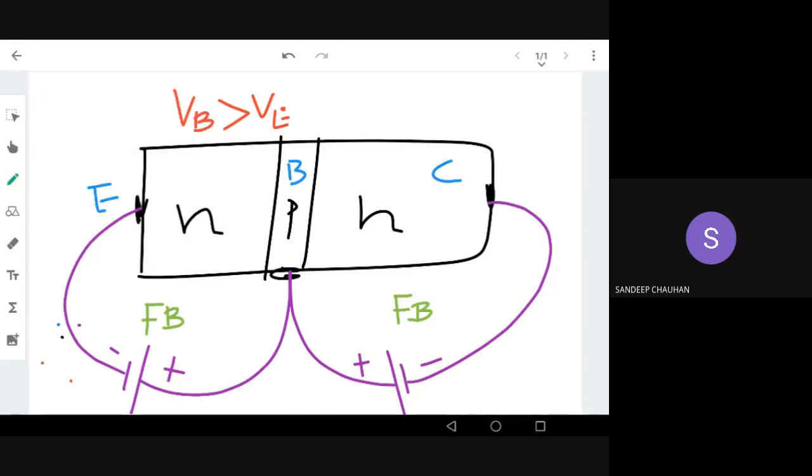The voltage at the base in this region is also greater than the voltage at the collector because of the forward bias here. And VB is less than VE also in the left region. So in this region, we call the transistor in saturation region operation. Based on the current magnitude and the internal motion of electrons and holes, we'll discuss in the next class how it works, etc.